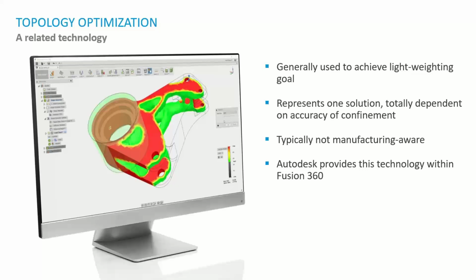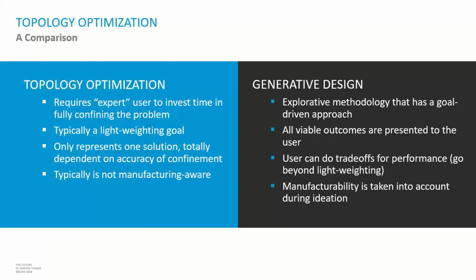I've taught that example. I've taught that workflow in my classes in the past. And so what I tell people is, okay, you're going to get this mesh file that you can A, 3D print, or B, push back into your CAD file and then use as a way of lightweighting. And that's the thought process behind the topology optimization, just lightweighting. We have a few more options when we go into generative design.